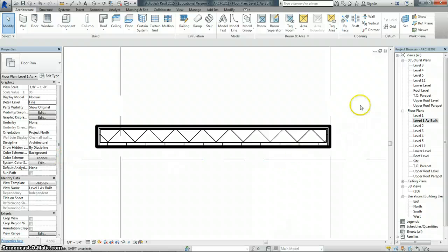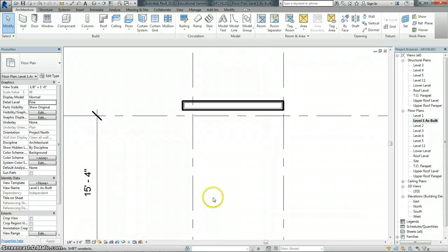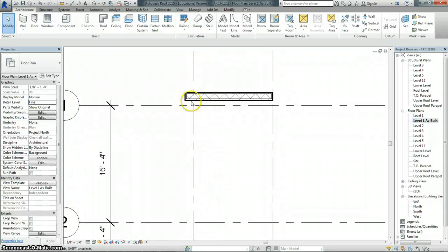Reason for that is I know that there was some question about how this will present itself because it was just a bunch of hatch, but you can see here that the wall concrete masonry unit, the insulation on the inside with the sheetrock, and then of course the wrap with the cementitious board, and the fiberboard panel on the outside wraps both edges of this wall. So as we add another wall to this, you'll see how that comes together based on the parameters that we built in class.